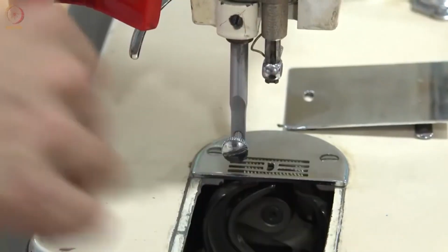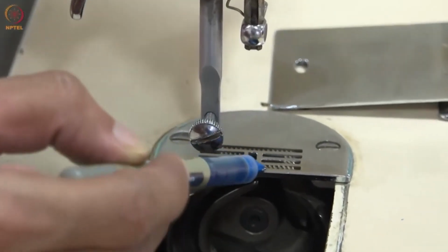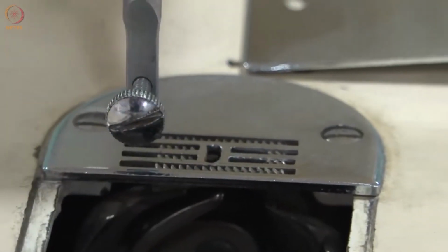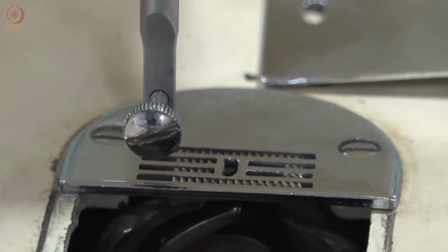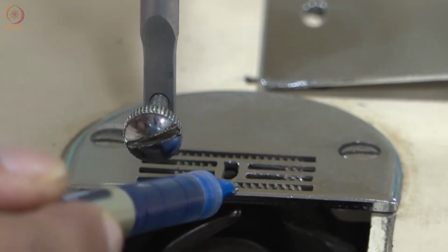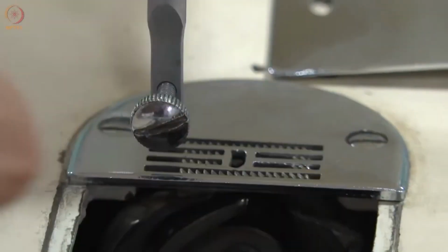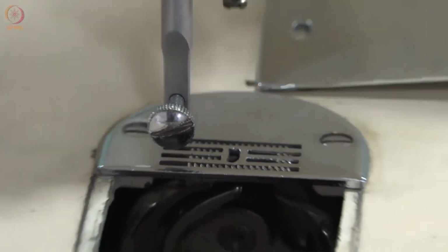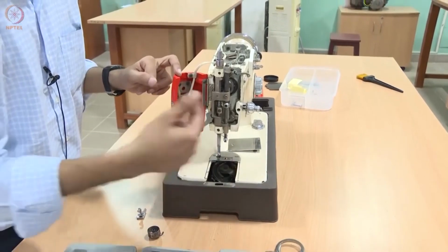So if you pay attention, you have what are called serrations, S-E-R-R-A-T-I-O-N. This is what we call a sawtooth pattern, right? This zigzag pattern adds a layer of roughness to the component that you see here. These serrations help latch onto the cloth and then pull it inward. So they help in advancing the cloth little by little. By using various knobs here, we can change the advancing length. In other words, we can change the pitch.